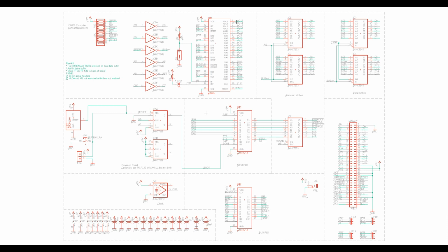What we do have is the Z8000 CPU here. It is a multiplexed address and data bus CPU, so these 16 wires have both the addresses and the data. So it has a pair of latches to latch the address bits and a pair of data buffers to buffer the data, and those are turned on and off at various cycles in the CPU.